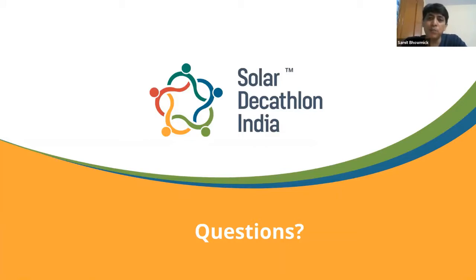So it really depends on how much information we get from the client and how clear we are about the requirement. But a typical safety factor would be in the range of 10 to 15% or so, the higher side being 20%. But again, we have to be careful. If you have very clear information or very distinct information about the equipment loads and lights and all of those things, usually we don't have all of this information when we're designing the first time. But if we do have them, then you might actually bring that safety factor down to about 10% or so, to 7.5% also, if you do have good information. So somewhere in the range of 7.5 to about 15% or so, as a rough thumb rule, so to say.